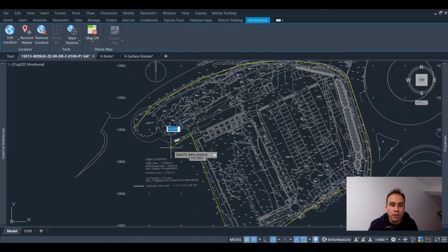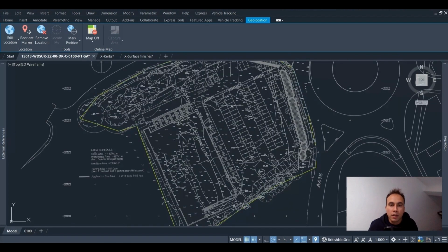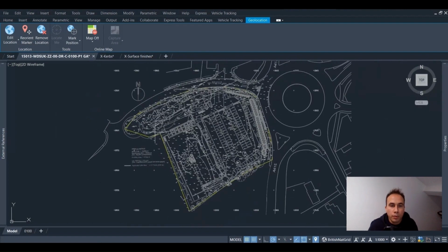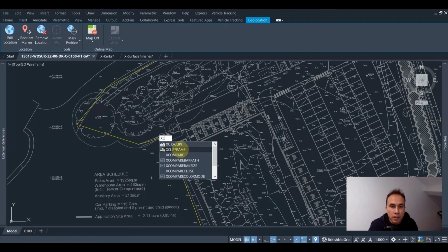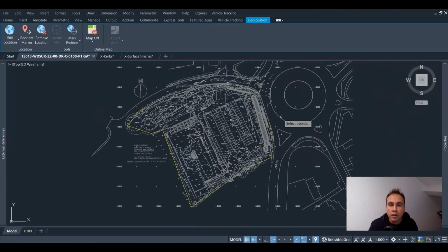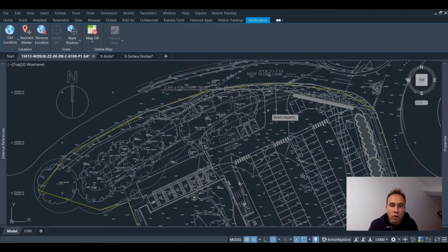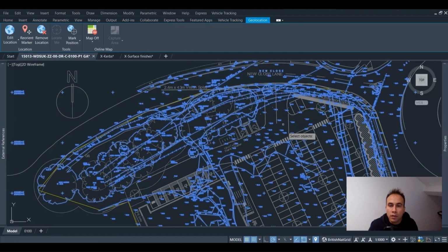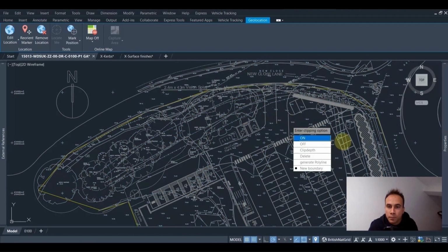For the sake of this video, we're going to close this polyline. We're going to create this shape quickly and use the XCLIP command. Check the XCLIP command in this video. We're going to pick the topographic survey drawing, new boundary, select polyline.